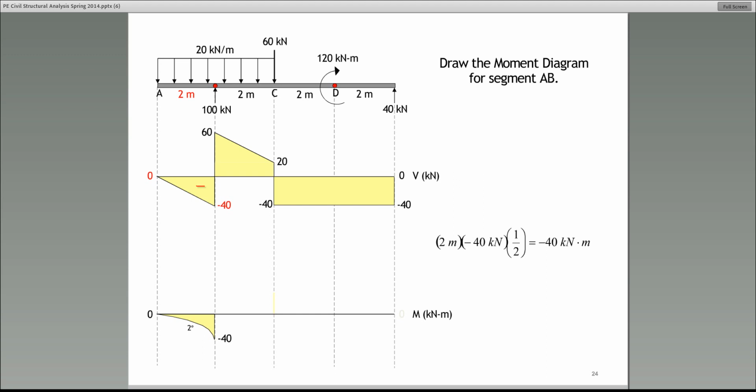Well, if you go to any reference book, let's say a strength of materials book or sometimes a statics book, they actually show several pages of calculations and they prove to you which one is correct. But I will tell you the quickest way to do this. I think Donald may have the idea. But guys, I will just give you a statement. I want you to write it down, and this will help you. The slope of the moment diagram at any point is equal to the intensity of the shear at that same point.